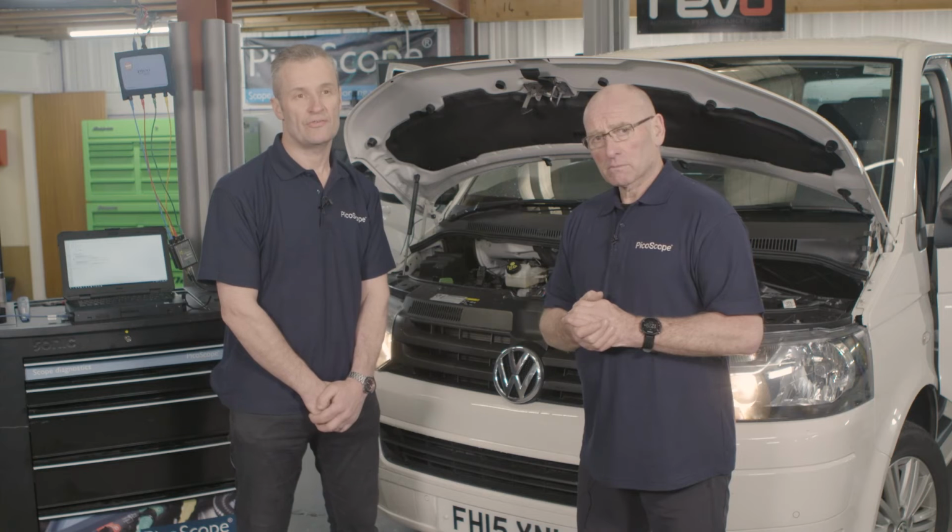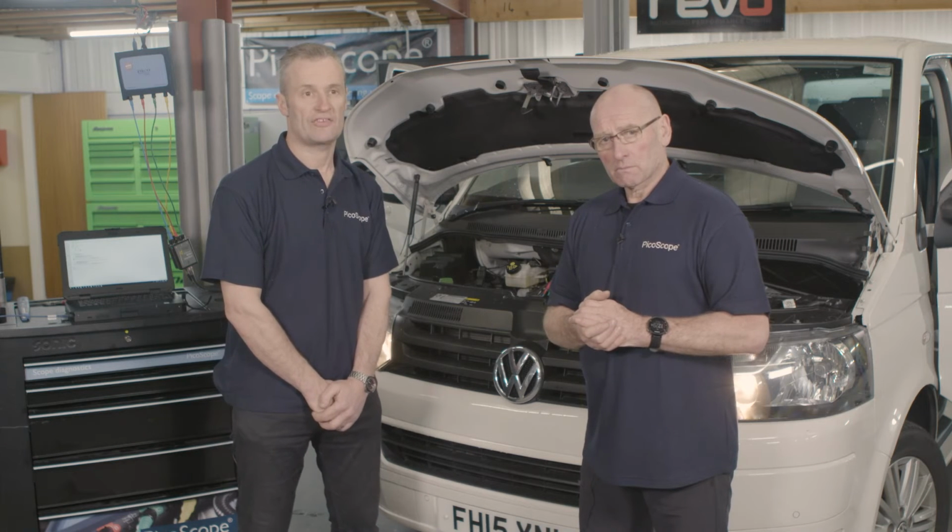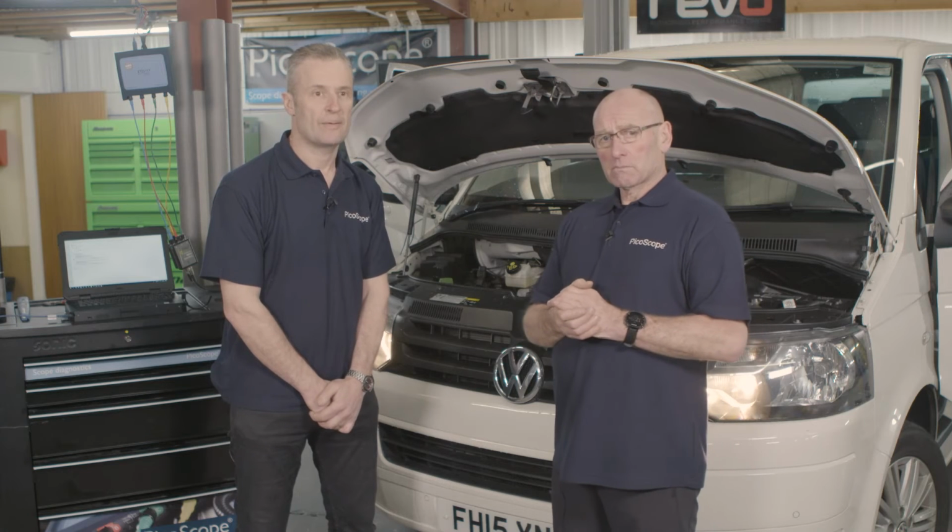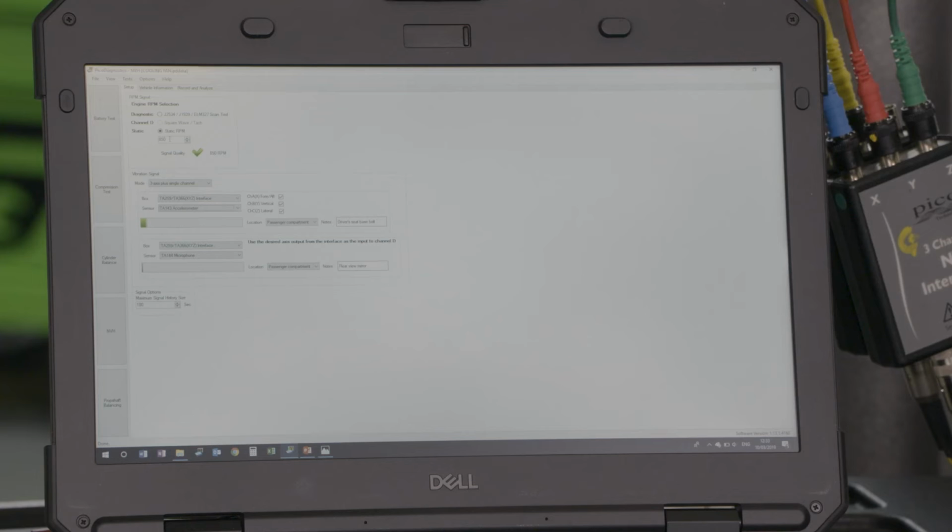Think of bearing noise if you've got the luxury of 4 microphones, 4 accelerometers, 1 road test, 1 measurement with a reference inside the cabin. Would you also recommend multiple microphones in the same way you would accelerometers? I would, most certainly, yeah. The advantage really of the accelerometers is we lose a lot of the ambient noise. However, the microphone gives a real, true representation of what the customer can hear. So always include a microphone in these kind of measurements as your customer reference, a representation of what the customer can hear.